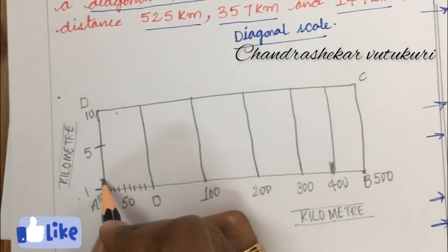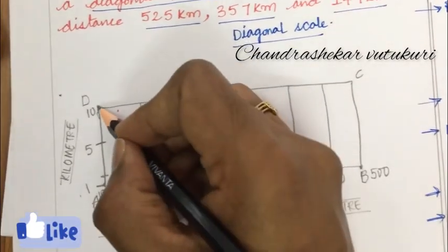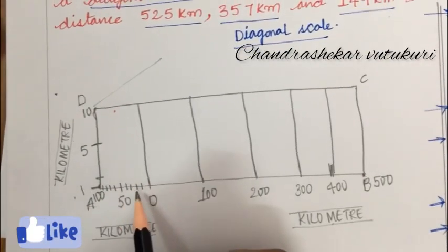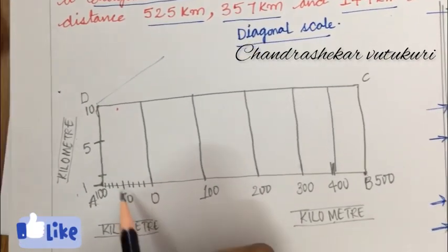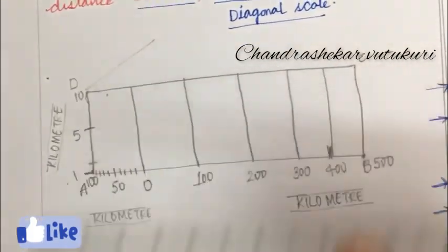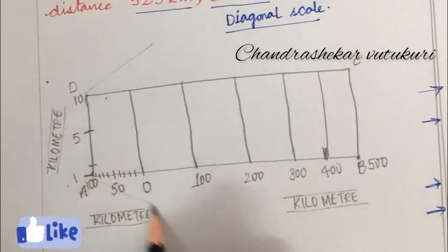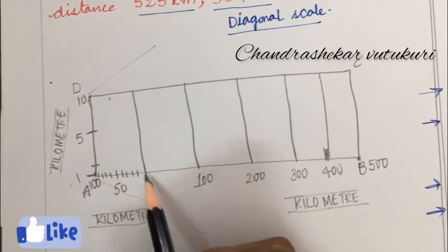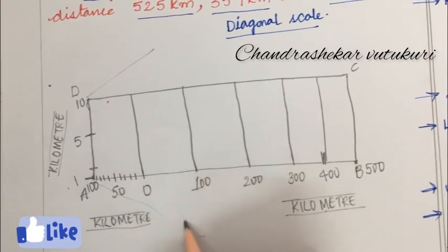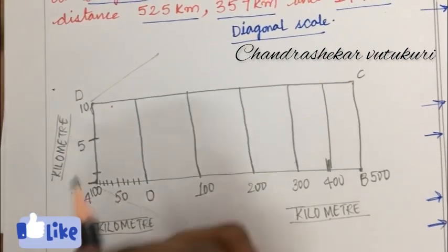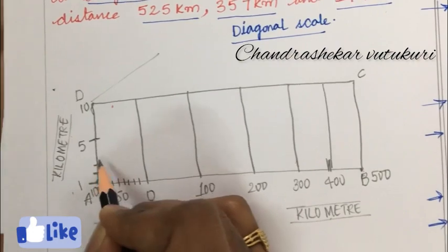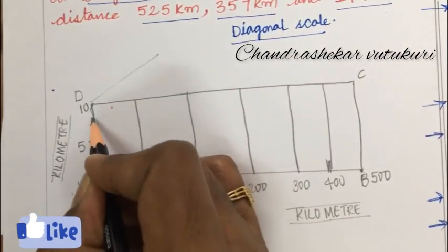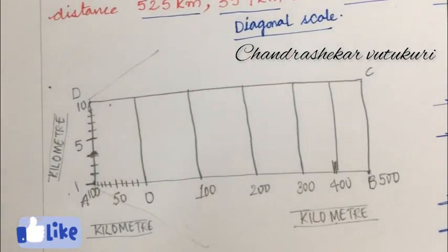Making a marking of that equally, either go with the dividing a line concept if you are unable to work out with the scale, or if you are able to divide as per the fraction or the decimal, you can go directly with the plain scale. If not, you are supposed to divide a line by the method, dear students. I hope you know you need to divide this into 10 equal divisions. The last division needs to be joined, placing the scale parallel to the last division and joining all the 10 lines. So, this is 2, 3, 4, 5, 6, 7, 8, 9, 10.